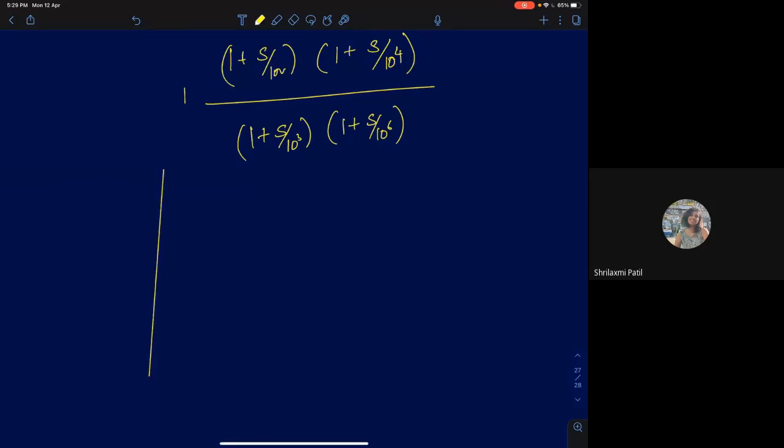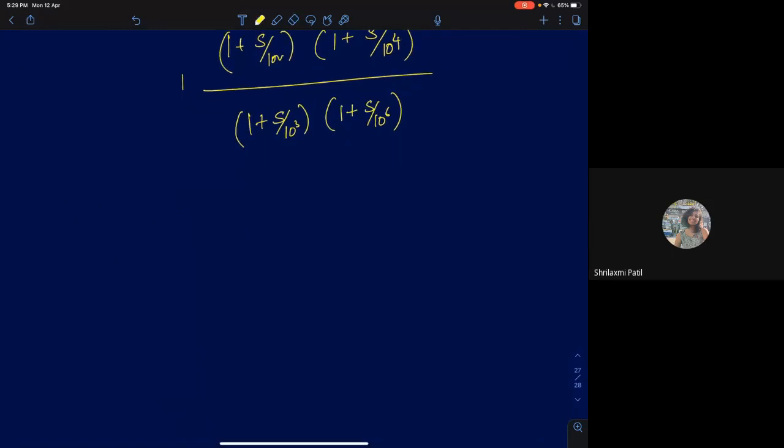So where do you think the graph will start now? Okay, so what will be the DC gain in decibels for the magnitude response of this graph? Zero decibels, right? DC gain is 1, substitute omega equal to 0, you get 0 decibels. So it's 0 decibels. Now the gain will remain constant.